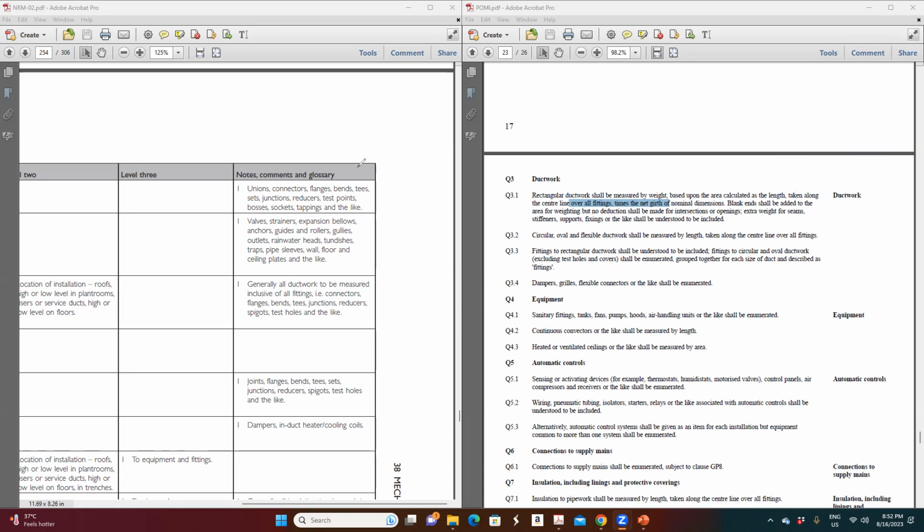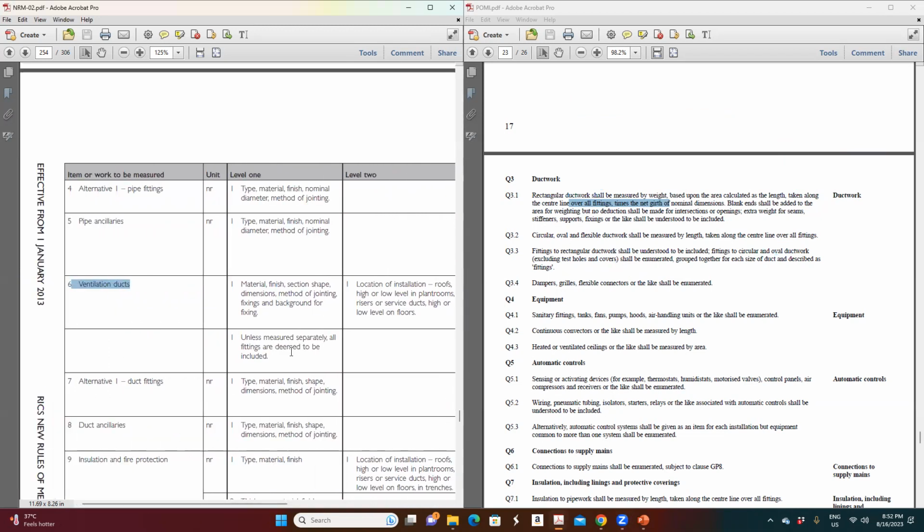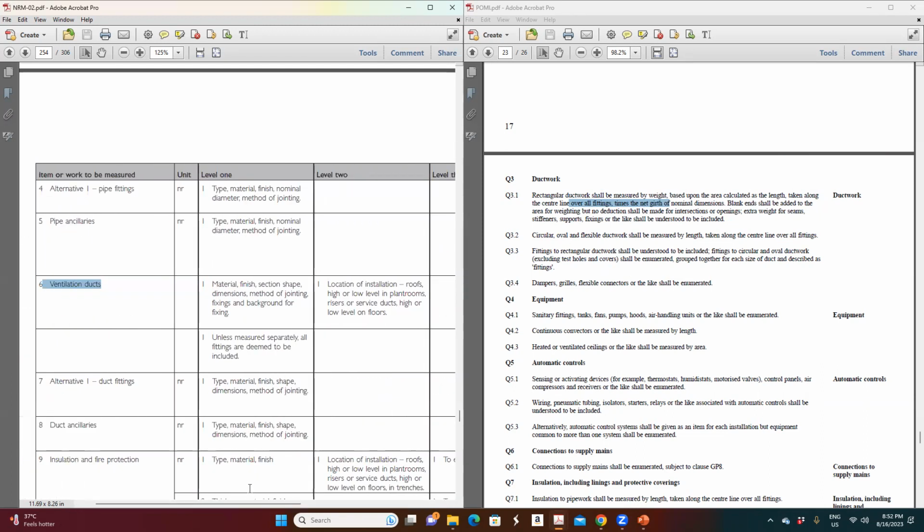Then, interestingly, they did not specify what it means, because GI duct was used in the old technology. I'm guessing, I don't know, I just need to do some investigation here. GI duct is used in old technology, but nowadays there is the duct called pre-insulated duct. The duct itself is already insulated. It's available in the market. You just bring it, fix the board, then tie it, join it and fix it on the building.